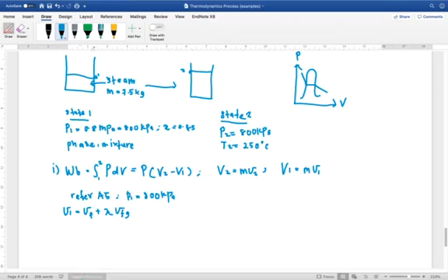How to find this value? Refer to A5 at pressure of 800. You will get vf as 0.001111, plus x, the quality 0.85, times vfg.